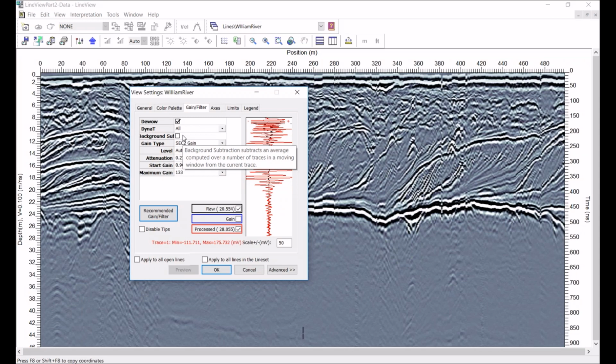This is a slowly decaying low frequency signal that may be induced onto the GPR trace due to a combination of how close the GPR transmitter and the receiver are from one another and the electrical properties of the ground. If you have a bistatic GPR system like the pulse echo, collect some data traces with the transmitter and receiver closer together than recommended, and you will really see wow.